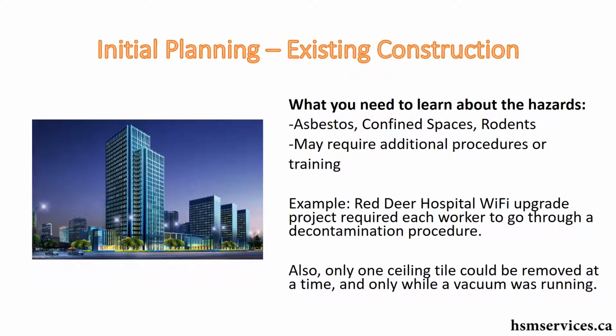And you need to look at the hazards. Is there asbestos, confined spaces? Are there rats and mice and things? That's going to complicate the project, complying with the safety, occupational health, everything like that.